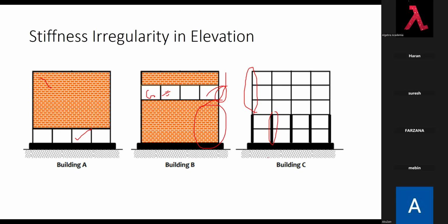Normally, in a building, the bottom story will obviously have a high shear force and axial force, so our size will be higher. Here we will have less axial force, so our section will be less. But what we have to do is not reduce the cross-section dimension as much as possible. We may slightly reduce the reinforcement and keep the moment of inertia as equal as possible.